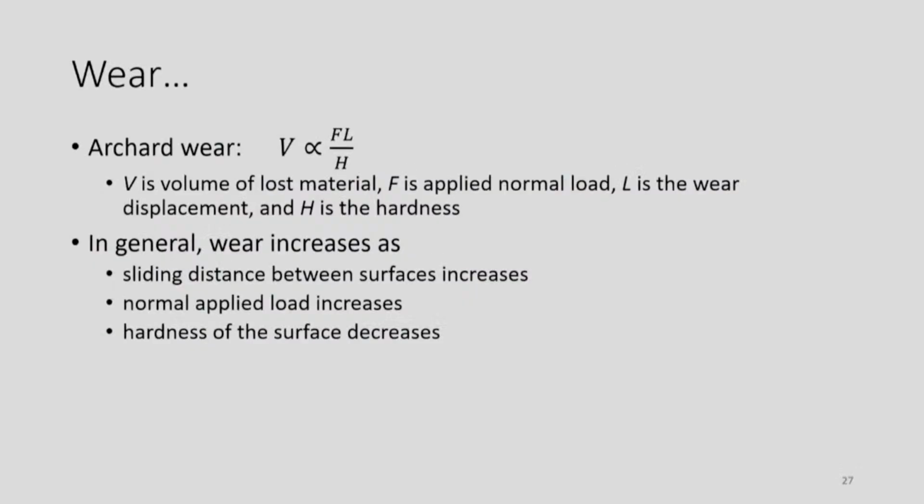But there are models. If you are again using DEM modeling for breakage, etc., then you will be using some models to calculate that wear. One common model is the Archard model. Based on the force that you apply, you can calculate the volume of material lost from the surface. Okay. So again, it's an easy calculation.